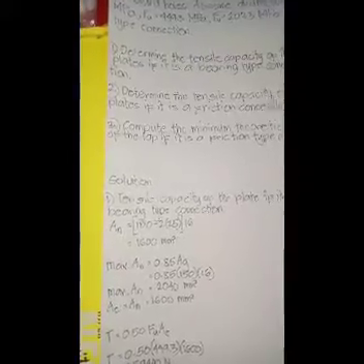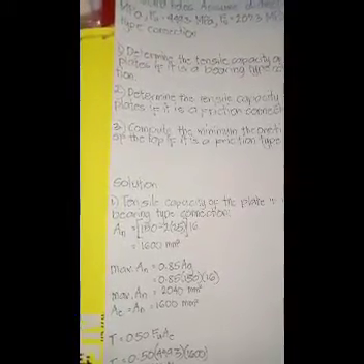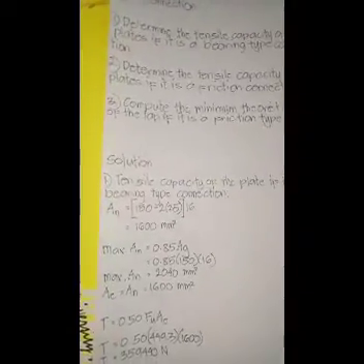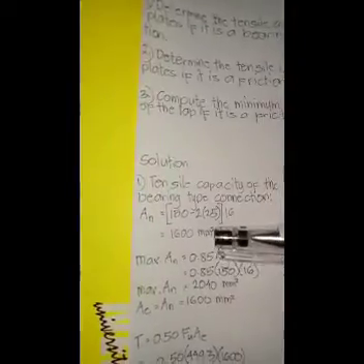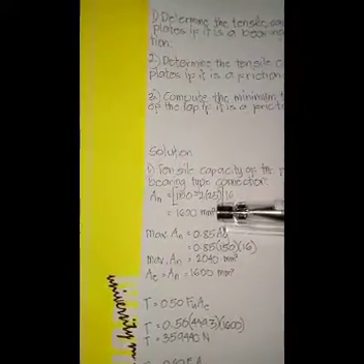The net area is equal to 150 minus 2 times 25 times 16. The 25 is because our diameter of bolt is 22 mm plus 3 for the hole, times 16 the thickness. Then our answer is 1,600 mm squared.